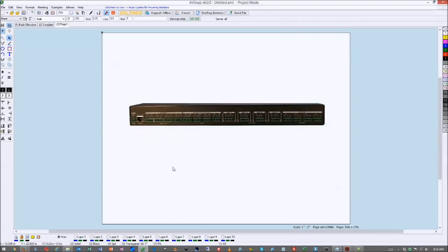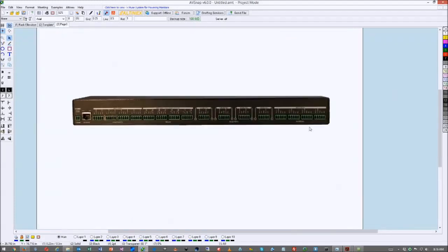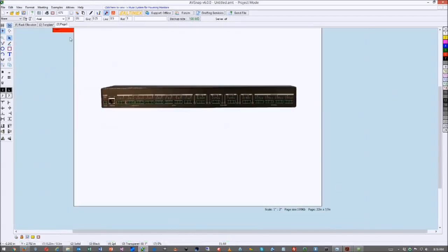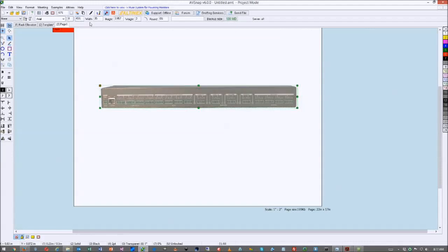And now that I pasted it in the home page, what I would like to do is to put a layer 1 from main layer. So I'm going to select the component, put to layer 1, and you can see there's a tab now for layer 1. And then I'm going to turn off the layer 1 by clicking on the green and blue rectangles right below the layer 1. I'm going to turn off everything so that it doesn't move and I cannot select anything, and I can draw on top of it. So in many cases, I will also select this object and make it transparent maybe, so it's not as prevalent on the page, and it's a little bit easier to work with.